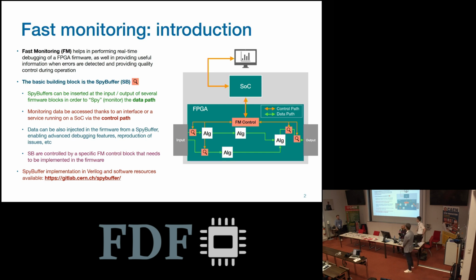So first, I wanted to make a comment, because I think there is a general misunderstanding, because this is very different from JTAG. We all do something like this in the high energy physics experiments, and the idea is that we keep this while it's running, and the data will be transmitted over the network of the experiment. So it's not something that you use in the debug phase. You plug in the JTAG, you see that it works, then you unplug it and you ship it where it works. So this is, as Iacopo was saying, in production phase while the experiment is running.